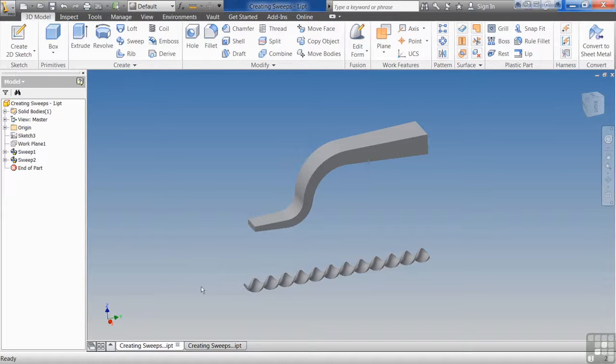Inventor does have a routed systems when you're actually adding electrical wiring to a part, but I deal a lot of times with store fixtures and things like that that are actually made up of structural wire, basically tubing or solid wire to create different shapes and objects that you'll see in a store. So you can use anything like that. You can use sweep to create that wire shape, but try to get creative with it. Think of how you can apply it in your situation and enjoy.